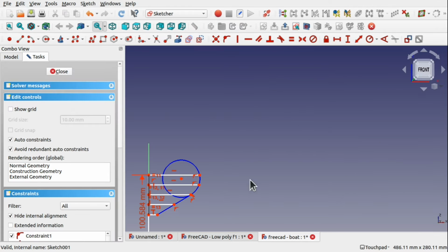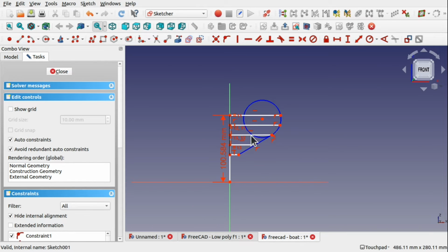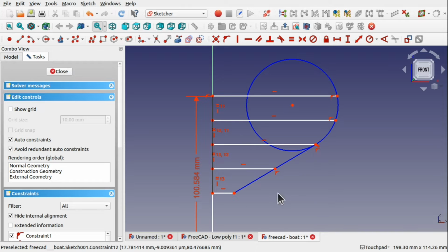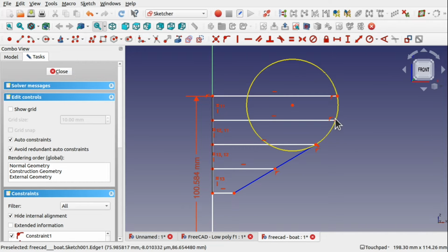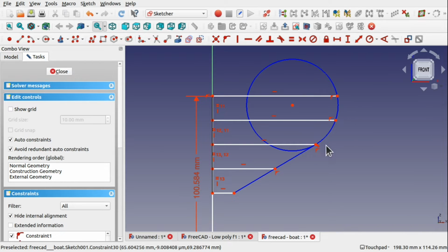So we've got this one here. This is the smallest one of the lot, so this is the front one, and you can see I'm working on the half breadth, so half of the actual hull itself, half the boat, and we've got these 3 lines here which denote the planks that go across the actual hull. These aren't planks themselves, they're just the points of where they connect, and you can see these are in tangent with this circle here, so these are in radius.